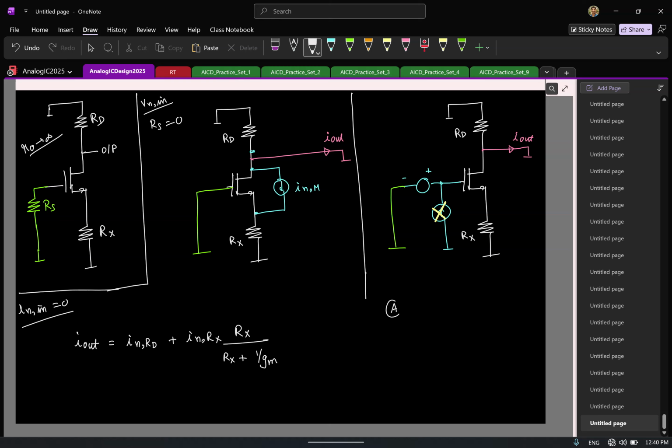Let us say you have two nodes A and B, and you have a current source between them. Let us say current I. I split it as two current sources with the same current I. Same, nothing has changed. Now, what can you say about the intermediate node voltage Vx? That is not defined. If it's not defined, I can define it to anything in the world. What can I define it to? I can make it 0. If I make this 0, then your job becomes simpler. This is grounded.